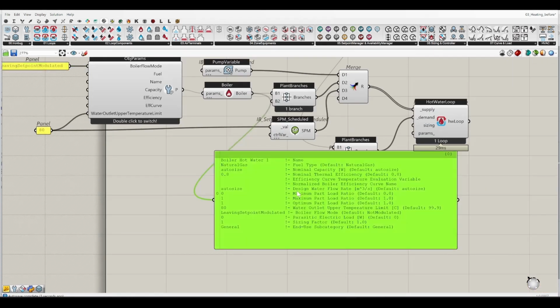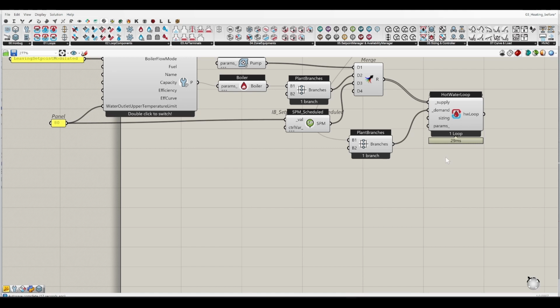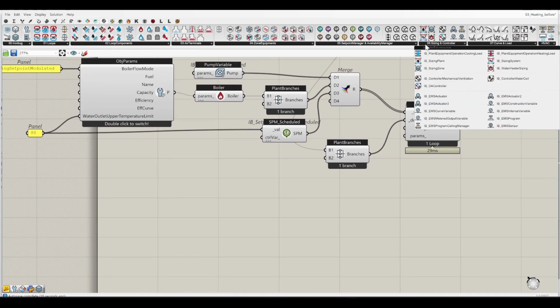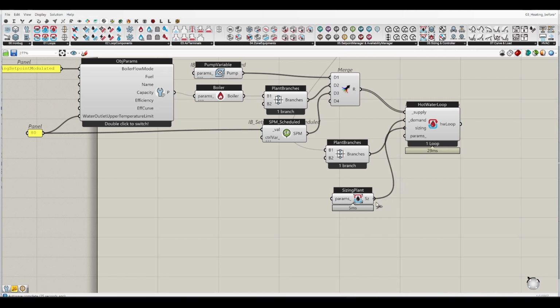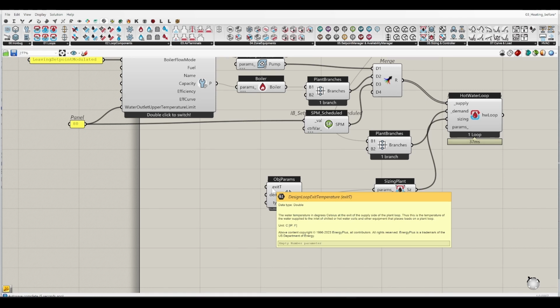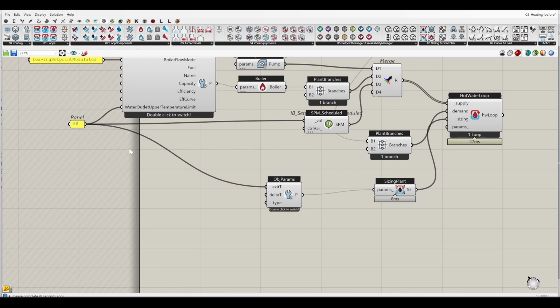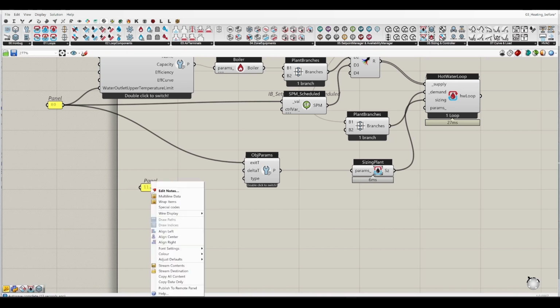And there are a few places where we need to match the temperature. One is the sizing controls for this plant loop. We can go underneath the sizing and controller to grab the sizing plant object parameter. So the design loop exit temperature, let's set to the same 80 Celsius, and delta T. Typically we use 11.1 Celsius for delta T, which is 20 delta T in Fahrenheit.